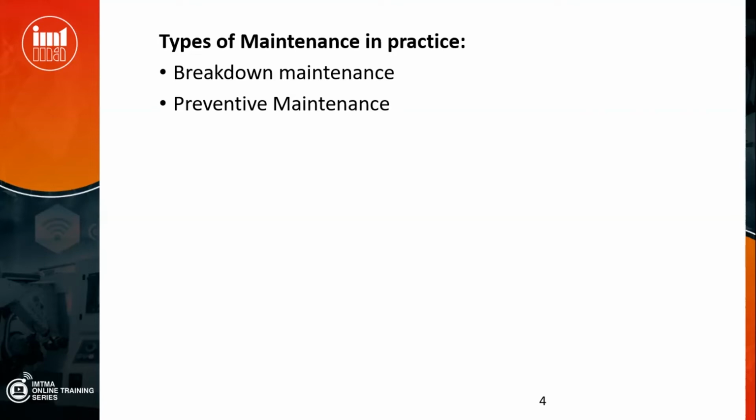The checklist is prepared. When I say maintenance, there is a procedure for maintenance. In preventive maintenance, you have to evolve a checklist: what to check daily, what to check weekly, what to check fortnightly. Your experience and the manufacturer's recommendation play a vital role in preparing the maintenance checklist. And many times we have seen the checklist filled up just by tick marks. Not that. Wherever it is possible, quantitative indication should be made.